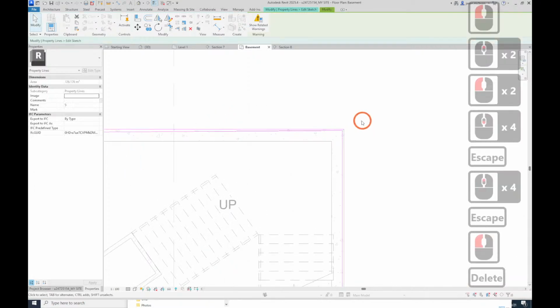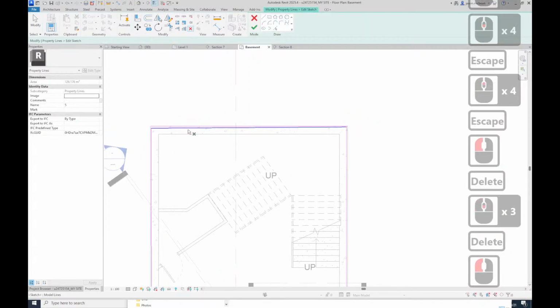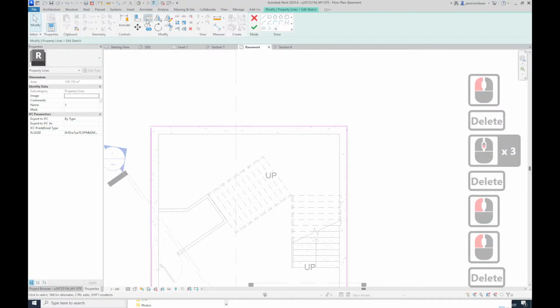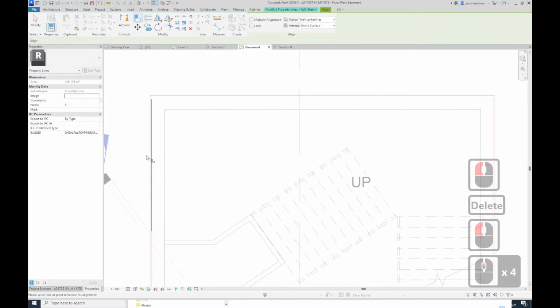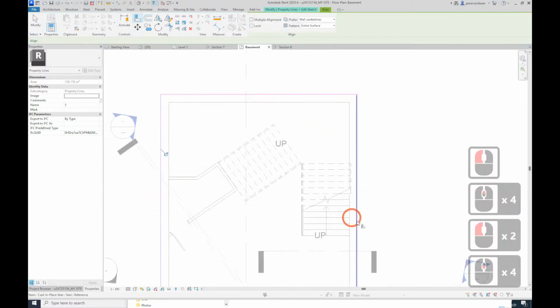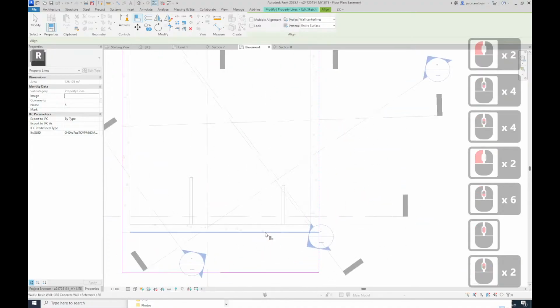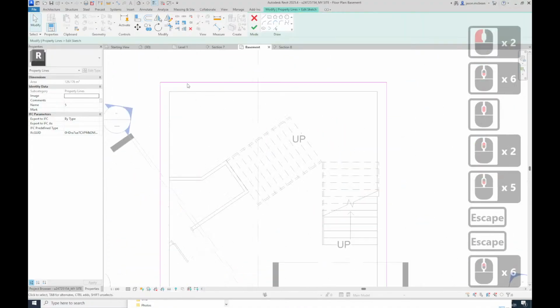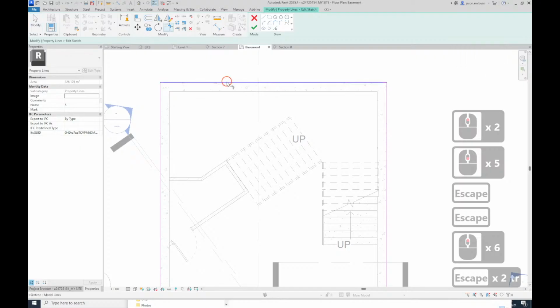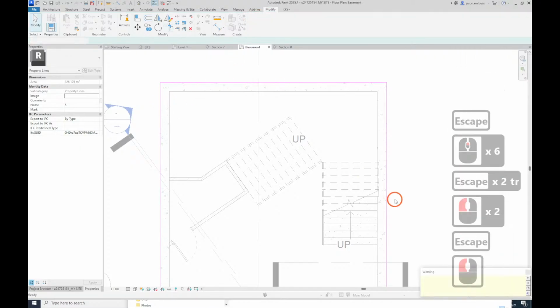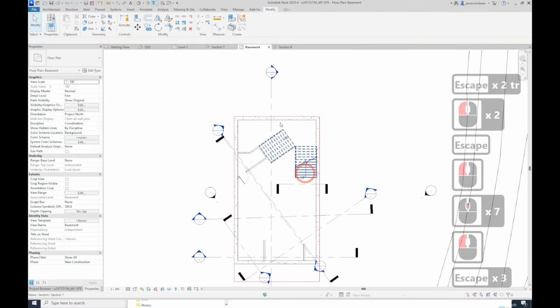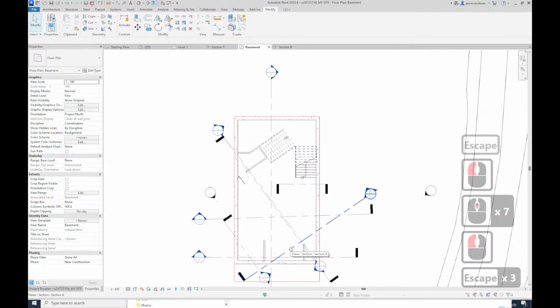Okay, don't do that. I use the line tool. Sorry, let's get rid of that. So you want to use the line command. That's how you tweak your property line. Just make sure that your adjacent buildings are not interfering either, okay? No, I don't think they are. Okay, then that's correct. Your front property line is good. Now going forward, no more problems with the property line. But that's a good thing. It's warning you, saying, woo, property line.